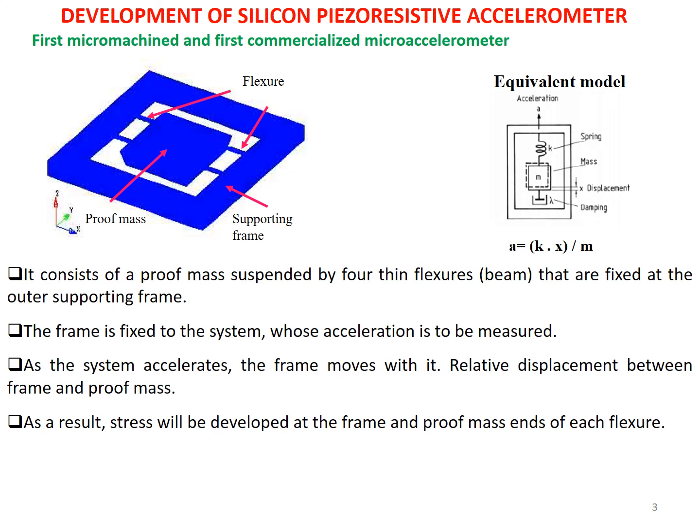Accordingly, some will show an increase in resistance, some will show a decrease in resistance, and that resistance configuration we can connect to a Wheatstone bridge circuit to convert the delta R into the delta V, right. In that way, the output voltage will be calibrated in terms of the applied acceleration. So this is the basic working principle of the piezoresistive type accelerometer, and this particular design is widely used. That's why we are describing this particular type of piezoresistive accelerometer sensor.